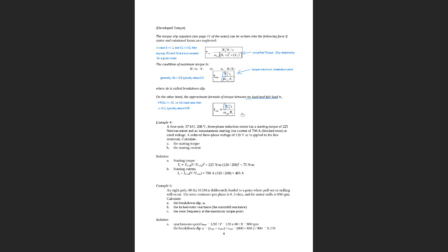Based on such a relationship, in practice we can take measurements of the torques and powers of the motors at full load, or at the breakdown points, so that we can determine the internal parameters. Or, based on given internal parameters, we can determine under what conditions and at what points the motor has the maximum torque.